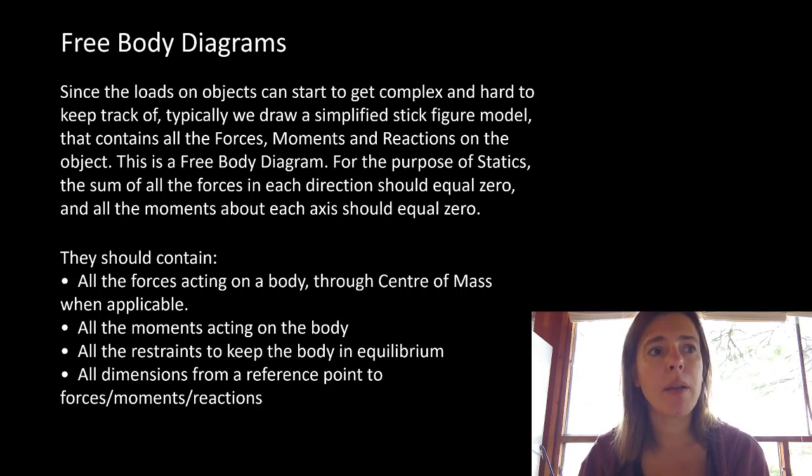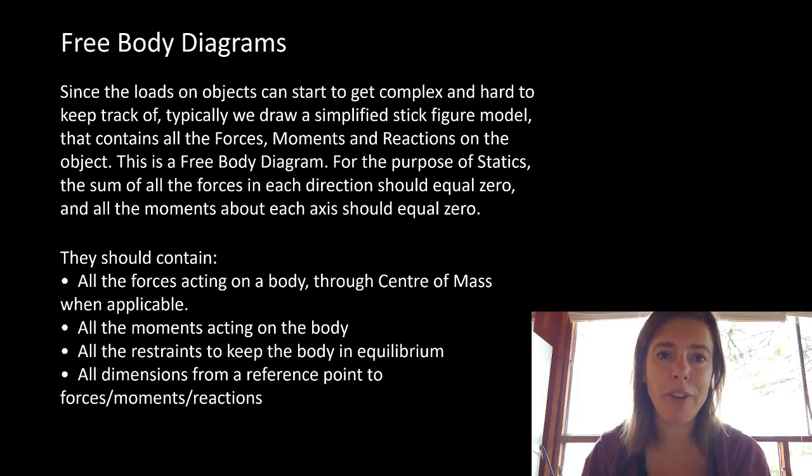So every free body diagram should contain all the forces acting on the body. And if that's through the center of mass, we kind of need to show that in some way. All of the moments acting on the body, any restraints that are keeping the body in equilibrium, which are technically also forces. Our reactions are still forces, but I find it handy to indicate which ones are reactions and which ones are forces. I'm probably going to be terrible at this, but my goal is to draw all the forces with a green arrow and all the reactions with a red arrow. I am sure I'm going to forget that at some point. In fact, I am thinking about two or three of the slides going forward where I have not done that. But that would be my ultimate goal in all the ones we're going to create going forward.